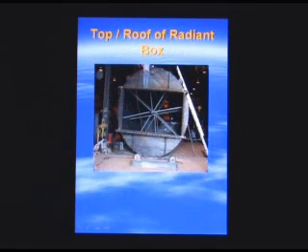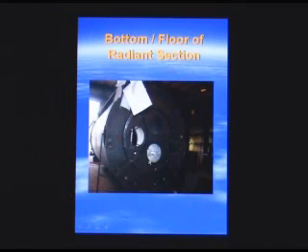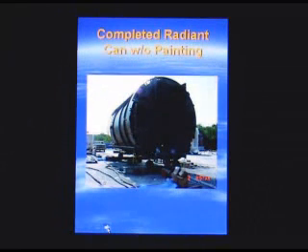This shows a top view looking into the convection section. It will basically mount on this plate, and you're looking into the radiant section down to where the burners would be. Again, this is a view from the opposite direction, from the burners out. This shows the unit with the radiant section fully fabricated. It shows you the support columns that are used to support the heater on pile caps, which was the proposed method of installation at DS1J.